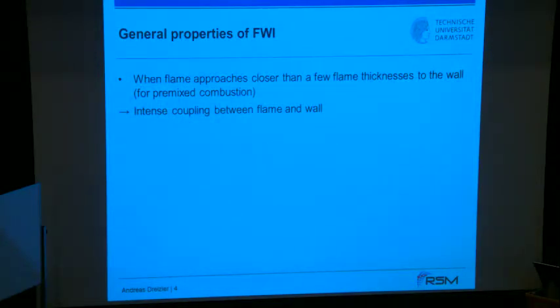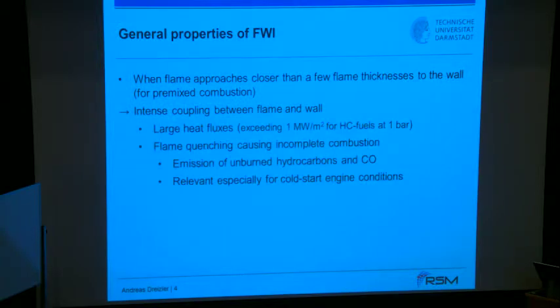And so for those of you who are not familiar with that problem, the most important properties are shown over here. We speak of flame wall interaction when the flame has come as close as a few flame thicknesses. Then the flame starts to sense the wall. Then you have an intense coupling. And of course, the most prominent thing is the heat transfer. And that can be huge.